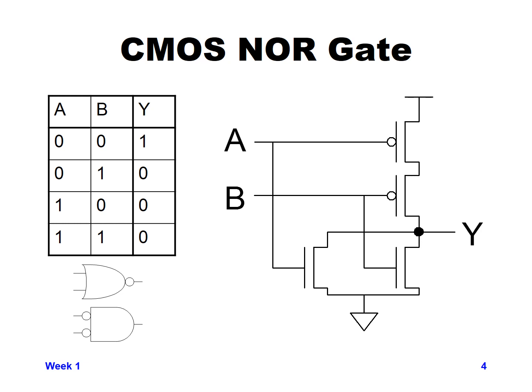So this circuit shows the other most basic logical function for CMOS, which is a NOR gate. In this case, it's similar to the NAND gate. We have 4 transistors composing this logic, 2 PMOS and 2 NMOS transistors. The NOR functionality is kind of complementary or flipped compared to NAND, where you can see in this case the 2 PMOS transistors are in series with each other instead of in parallel.